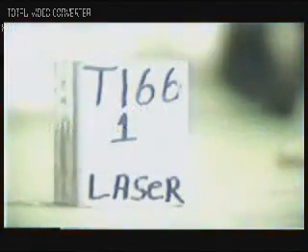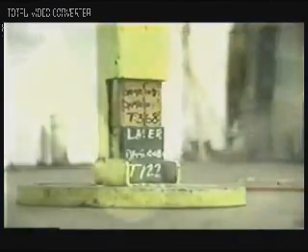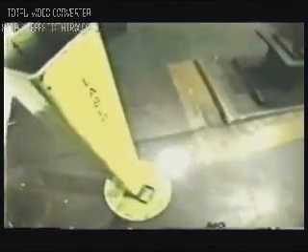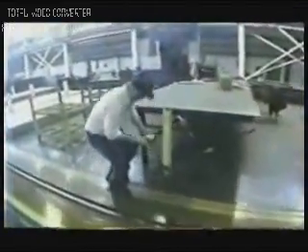Depending on the particular material, we have several different replenishment procedures. For example, in the steel area, we use a steel sleeve that's triggered when a Kanban becomes empty at the workstation. The technician will pull that sleeve and place it on a board over by the wall where our logistics people log it in, and it triggers a supplier to order more material. As materials are consumed, which we replenish in-house, the technician takes the sleeve and drops it into the FIFO tube, which initiates the replenishment cycle.